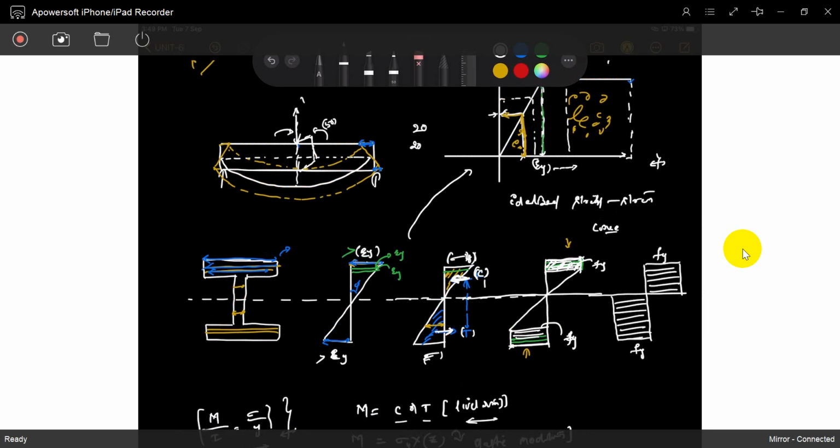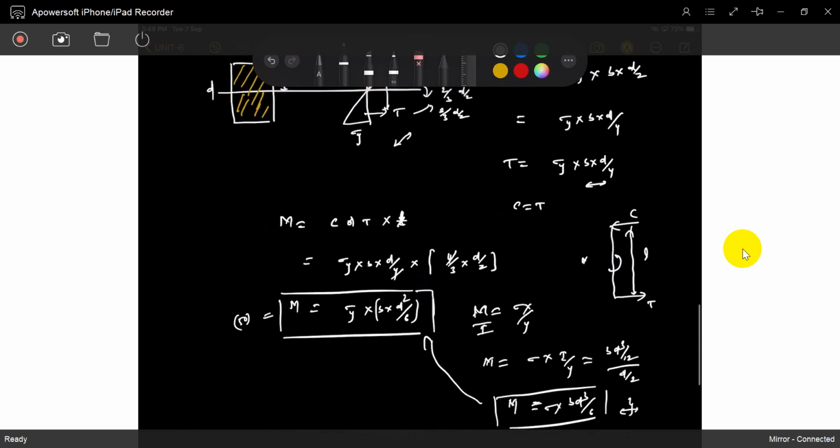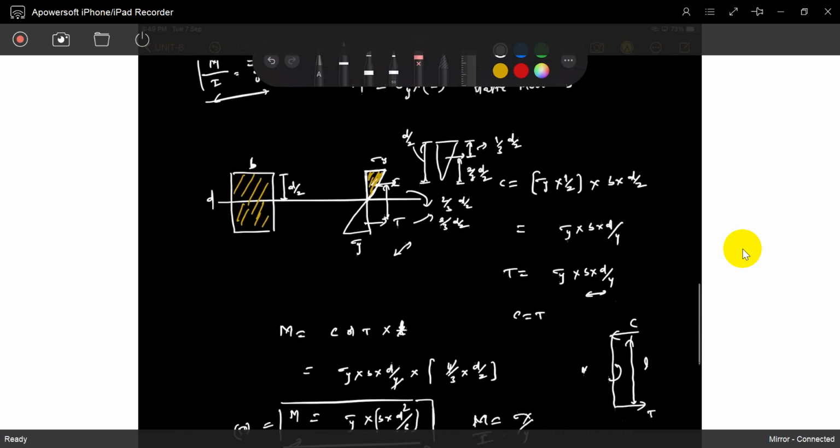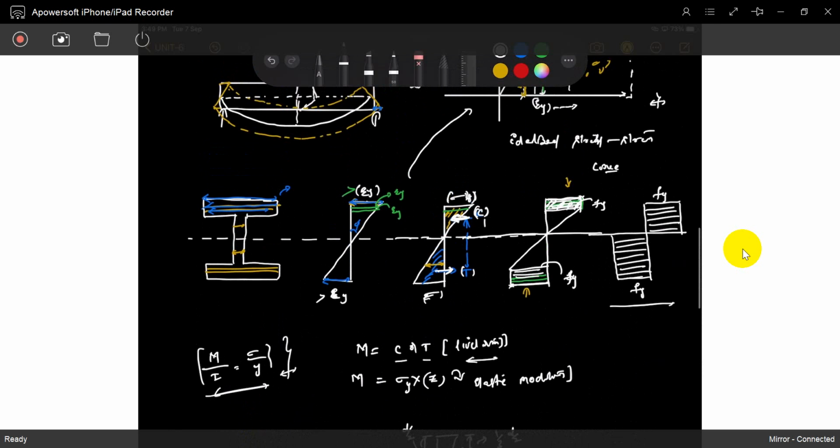Now if you consider what is the section capacity in plastic analysis? This is the elastic section capacity, elastic analysis section capacity. Now you see, this is the real, not an ideal, total capacity of the section. So now this is a compressive force, this is a tensile force, this is a lever arm.